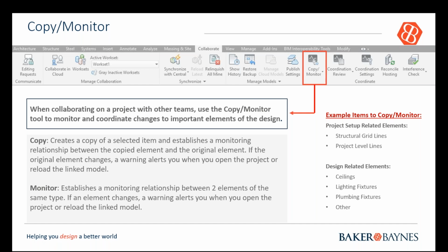And if you're an engineer and you're sitting in here and you're not sure of it, then you should definitely be clicking on that. So what this button basically does is, I'm going to use the built environment again. We have the architect's model, so I'm maybe the architect, and the structural engineer gives me his or her model. And now instead of me creating duplicate floor slabs, I'm going to link in the structures Revit model and work off of my model. And if I created my own floor slabs, I would now see floor slabs from my own architectural model and that of the structural engineer.